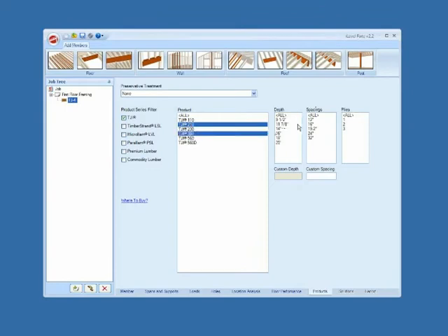210s and 360s, 22, 24. You can also put in a custom spacing and custom depth for rectangular sections. You can do custom depth. Depending on what type of member you're sizing, you may or may not see some certain categories appear. Like if you're sizing a post, you're not going to see a TJI as an available choice because TJI cannot be used in a post application. So you will see some of these fluctuate and change depending on what member type you're designing.